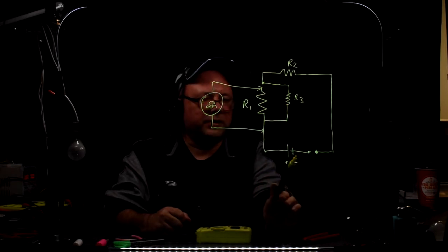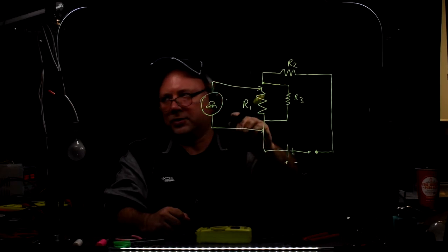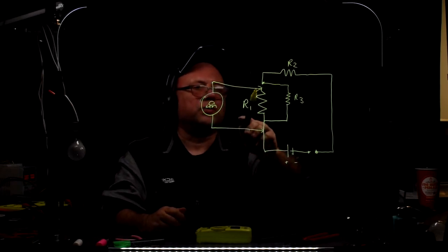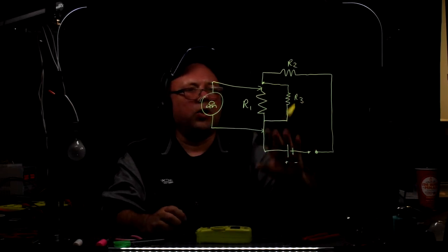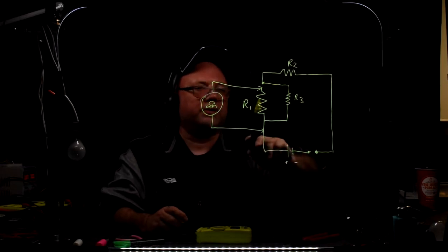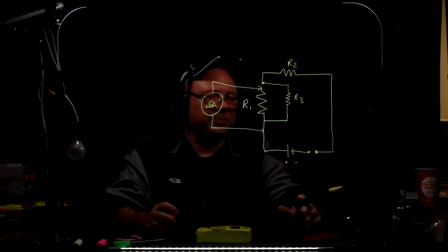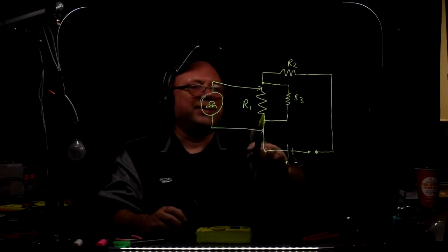However, we should de-energize the circuit, because now we are removing one component out of the circuit. And sometimes when we remove a component out of the whole circuit that's not supposed to be working as a whole, then you can actually damage whatever the circuit is by removing a part. Not always, but sometimes it happens. So de-energize the circuit, disconnect the resistor.